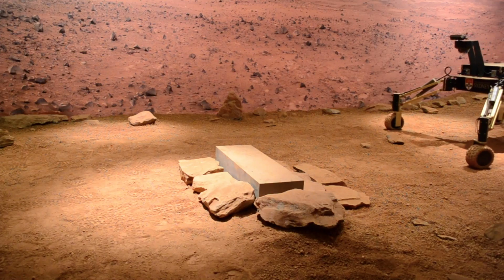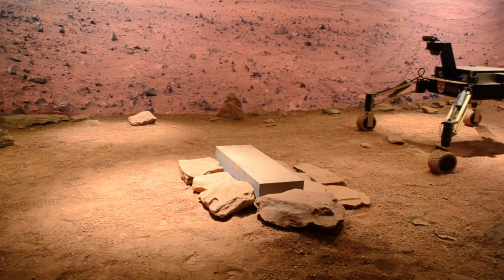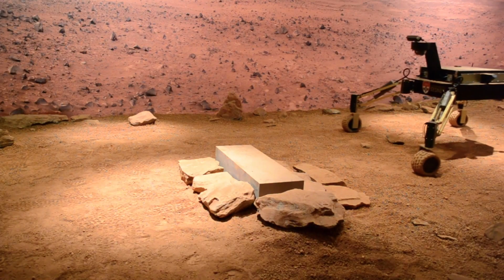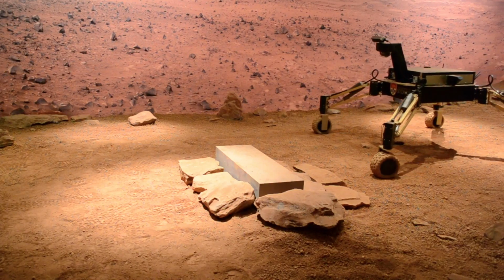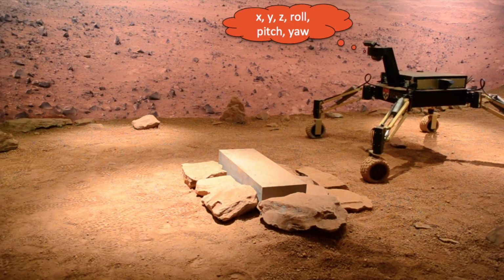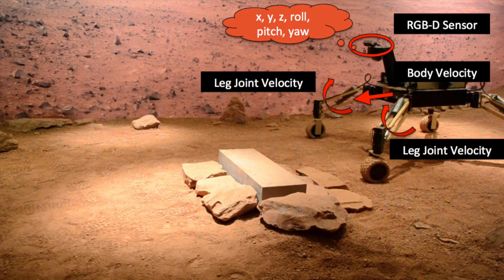To demonstrate our development process using Simulink, we will summarize the implementation of an example motion control task called actively articulated suspension. The objective is to get Mammoth to localize itself and perceive the terrain around it using an RGBD sensor mounted on top of its head. The vehicle operator then gives the rover a desired forward velocity. The vehicle must maintain this velocity while keeping a constant pose by actuating its legs and conforming to the terrain.